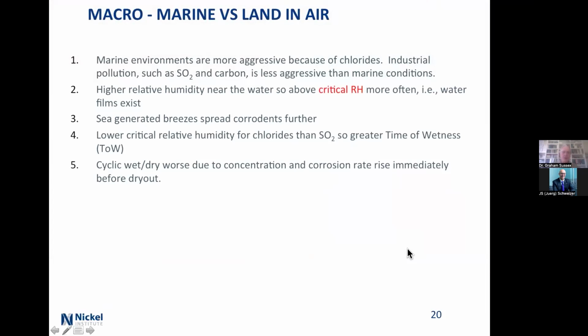Okay, let's look at the macroscopic things. Marine environments are more aggressive because of the chlorides and industrial pollution from sulfur dioxide or carbon particles landing on the surface. That can be quite aggressive. You've got the carbon to steel potential difference, but you've also got the crevice around. So marine environments are not good.